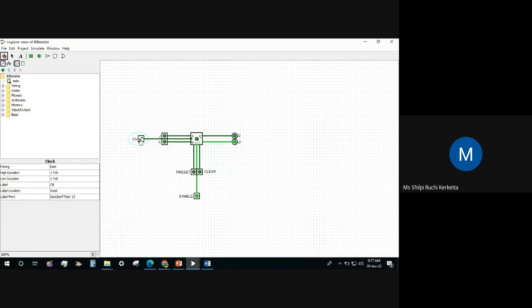So we will put a clock. For 0, it is not working because it is positive edge triggered. Again, when we give 1, for JK 1, 1, Q is 0 and Q bar is 1. With 0, it is not changing. But if we give it as 1, you can see it is just reversing.